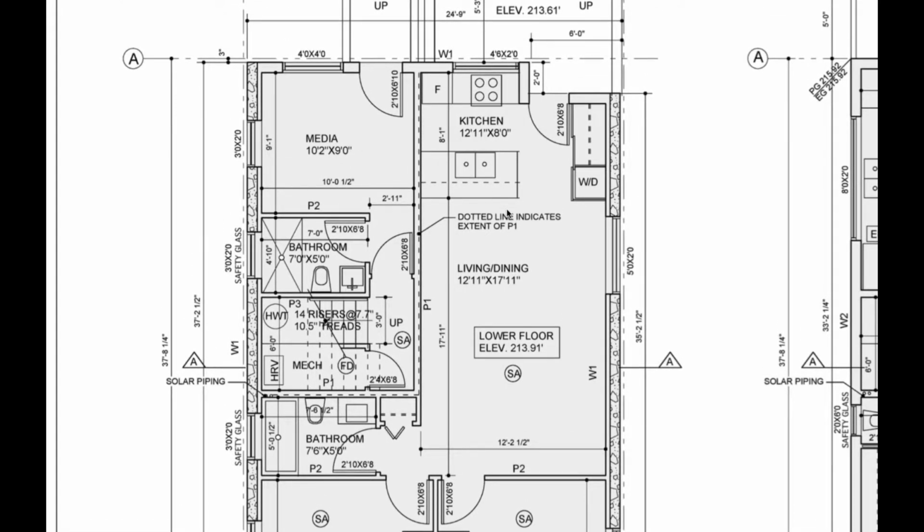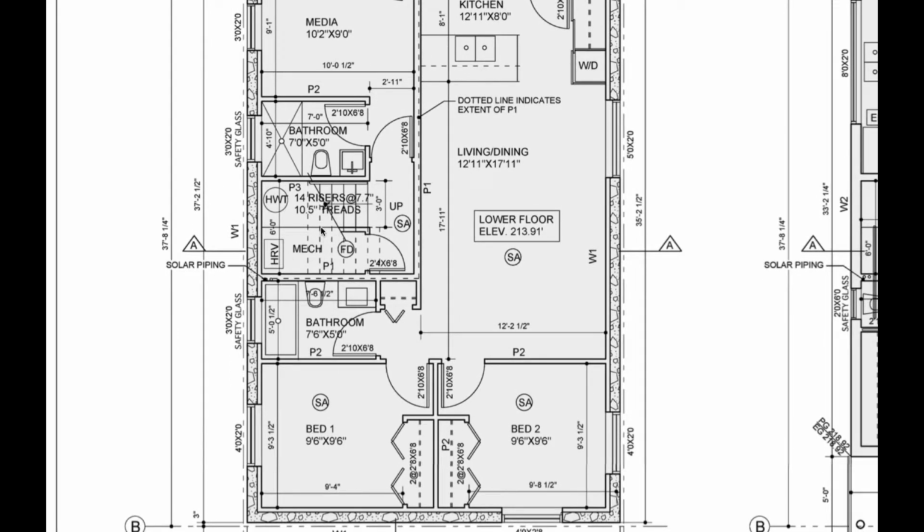So it's really good to get that in your head ahead of time, that you're going to be able to locate and do your rough openings for your windows in the actual concrete. So you have to lock that away. That also means that you're going to need to put in headers afterwards to support the floor joists for the next level, or the floor system that goes across those gaps. So there's going to be a staircase down there, which is good.